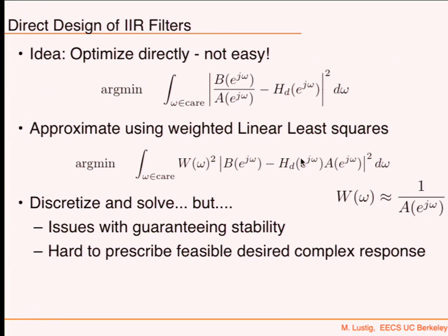And it's more complicated. With an FIR, you just shift it, but an IIR is not as trivial because it has an infinite impulse response. So we can't just shift it. If you crop it, then it's no longer an IIR. So with all of these issues, you have to come up with the right phase. Then that would result in something that is stable.